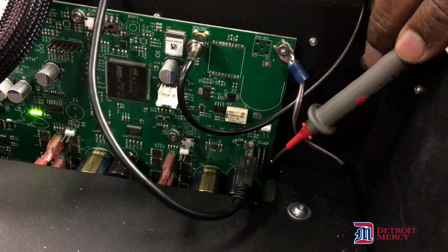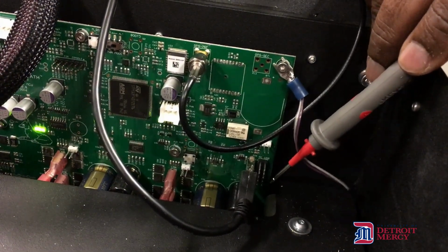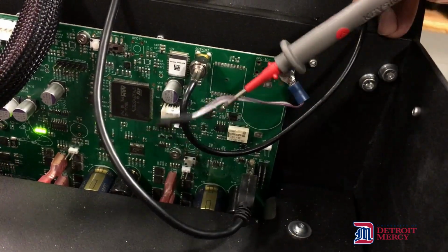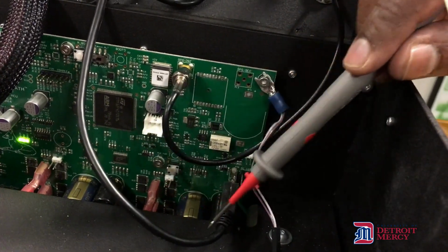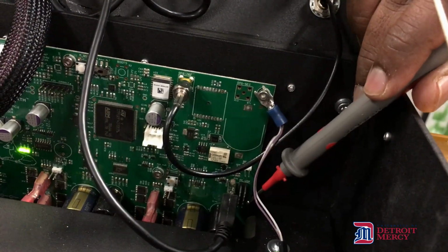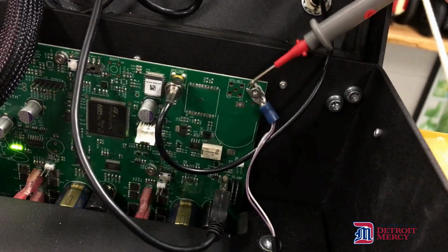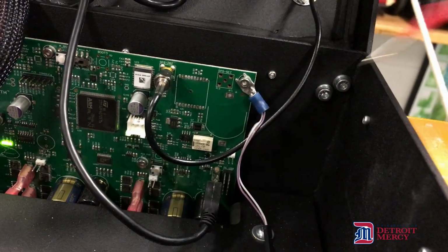So on both sides, the fourth pin is ground, and we are going to use this wire to connect to that ground. So what is going to happen here is the ground which is coming from the NUC will be coming here, and this pin we are going to connect to the chassis of the Jackal, so that it is going to be a common ground.